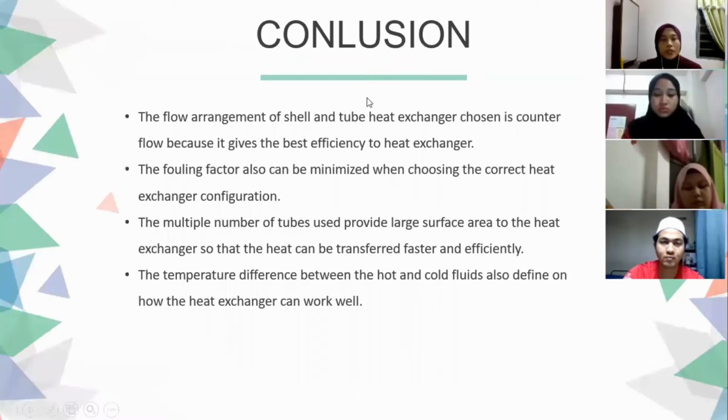So for the conclusion, our chosen heat exchanger is design three, multi-pass with counter flow arrangement, because the flow arrangement of the shell and tube heat exchanger chosen is counterflow, which gives the best efficiency to the heat exchanger, and the fouling factor can also be minimized when choosing the correct heat exchanger configuration.